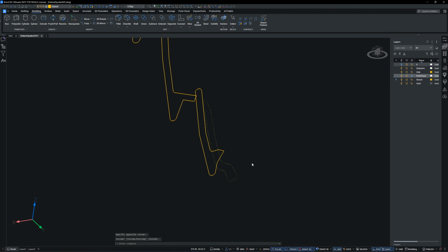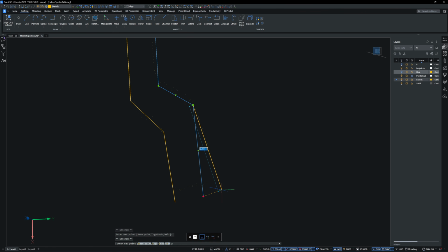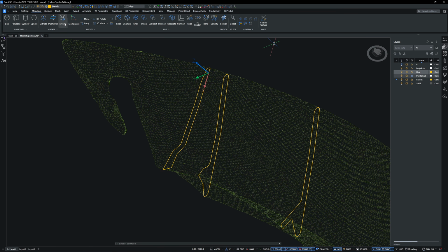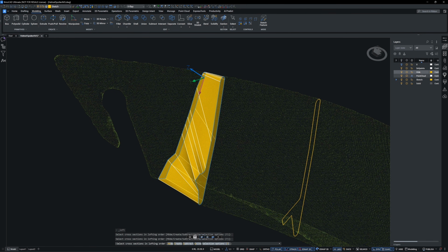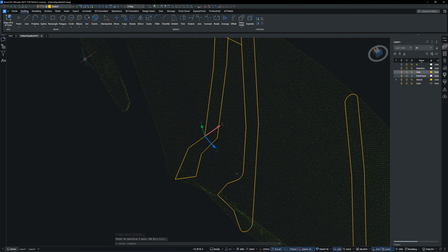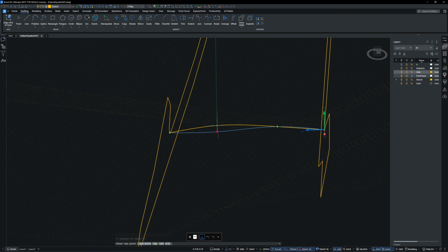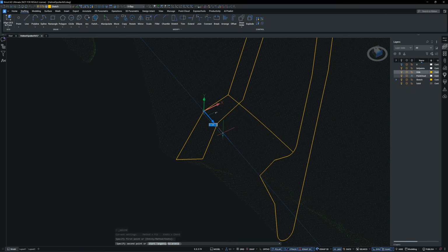Now I'm modeling the hook section. Since this part changes shape within a very short distance, I need to create multiple profiles to replicate it accurately. This section requires guide rails because the profiles differ too much and need rails to form the surface correctly.